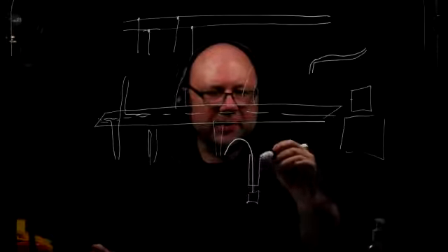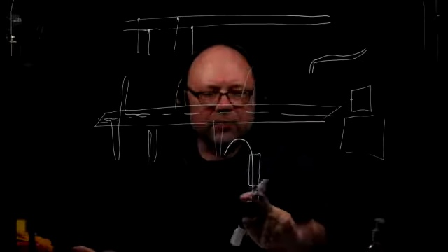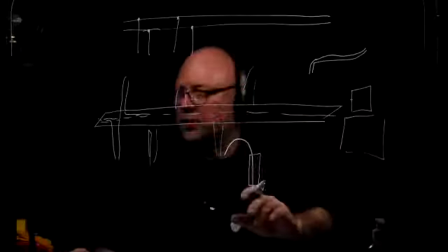And I put a little bit of an EMT pipe on the desk, so that's going to simulate the pipe in the wall, right, the conduit in the wall. And that is going to be connected to a utility box, and the utility box is going to accommodate the volume control. Now, that wire that's coming out, we're going to label those as we have mentioned in the lab instructions.